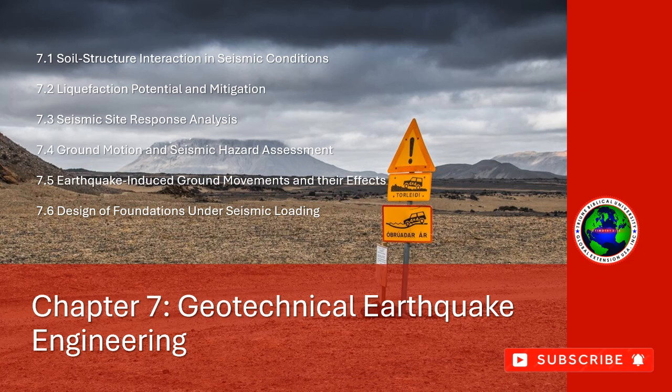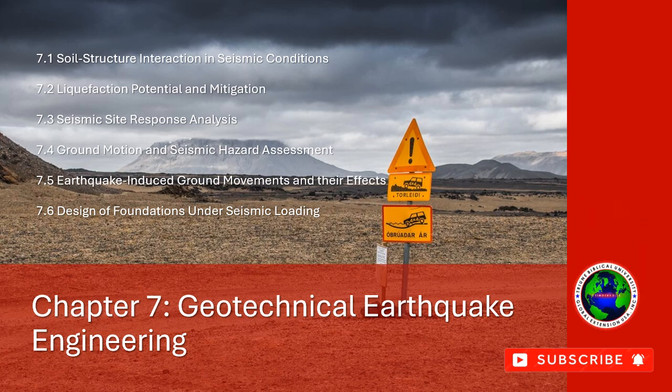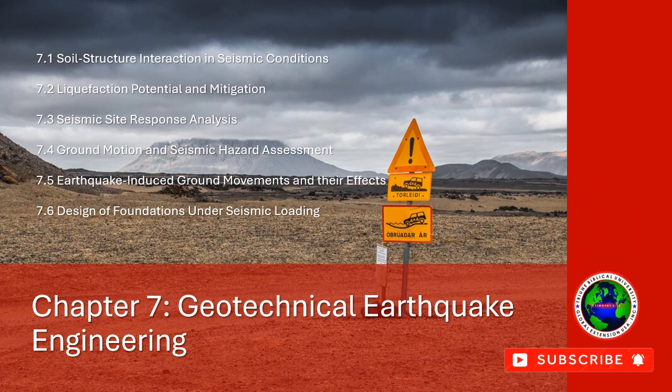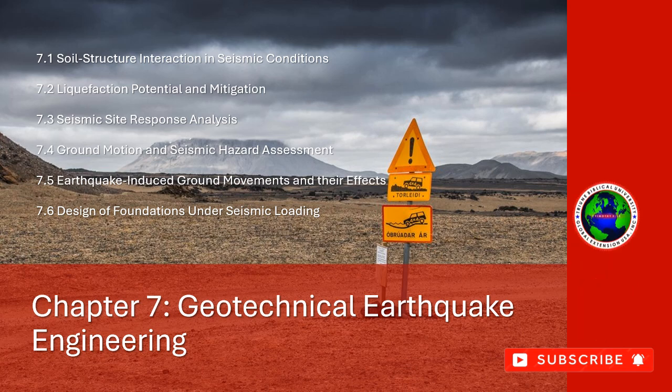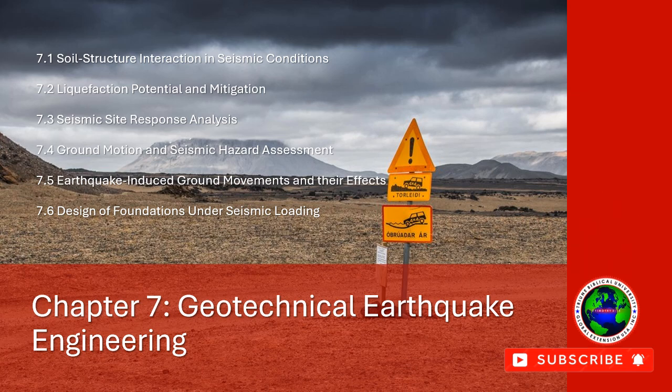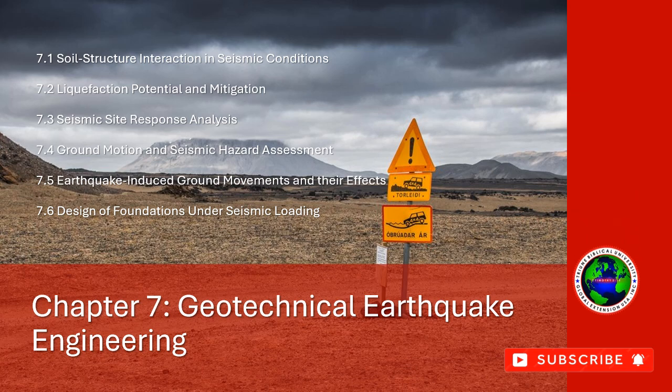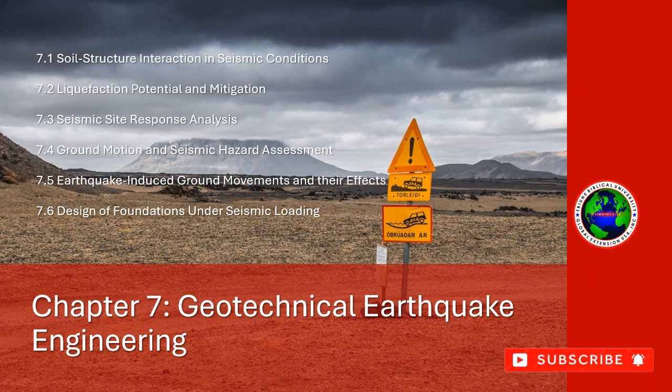3. Nonlinear site response analysis. Nonlinear site response analysis is required to model soil behavior under strong shaking conditions, where soil stiffness and damping properties change significantly due to plastic deformation. In real-world earthquakes, the soils may experience large deformations, and a linear model would not accurately represent the behavior of the soil.